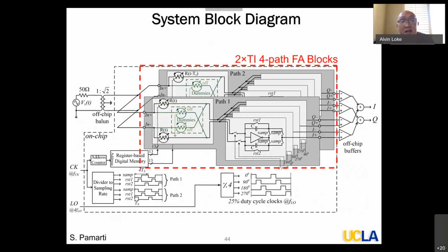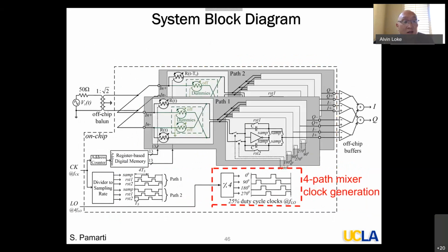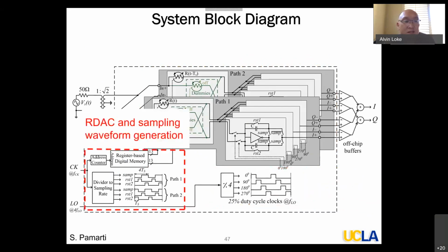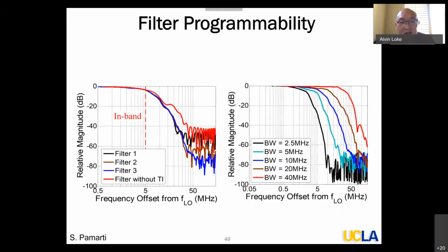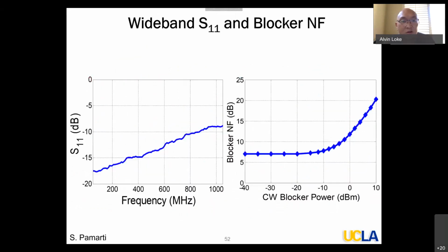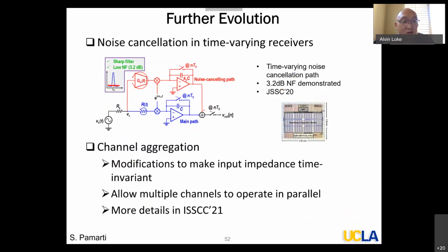And I'm assuming in all your switches, since you're very meticulously integrating charge and so forth, all the standard tricks like offset cancellation, for clock feedthrough, for charge injection, all that's probably stuff you have to pay attention to get this level of performance, right?